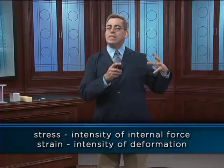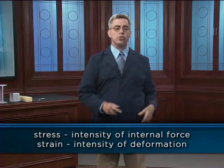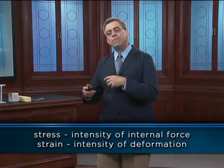Okay, that's stress. Next, Augustin Cauchy's second contribution to today's lecture is the associated concept of strain. Just as stress is the intensity of internal force, strain is the intensity of deformation. As we saw in Robert Hooke's experiments, a member loaded in tension elongates. Strain is a way of characterizing this elongation in a particularly useful way.